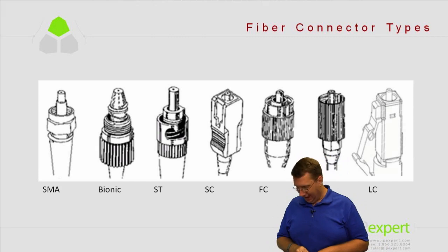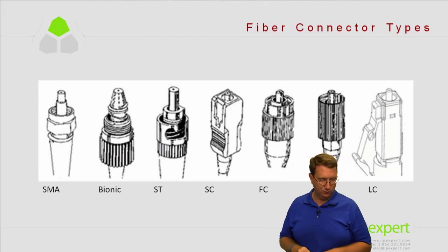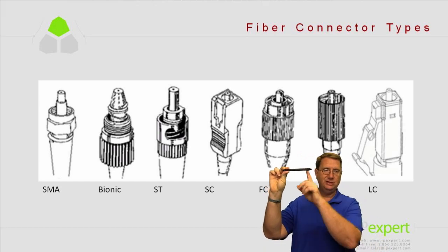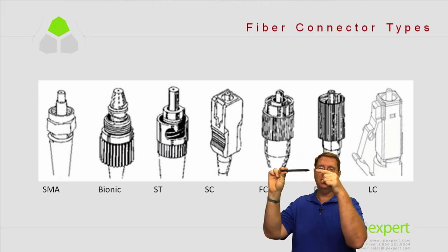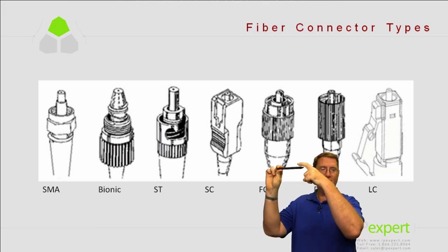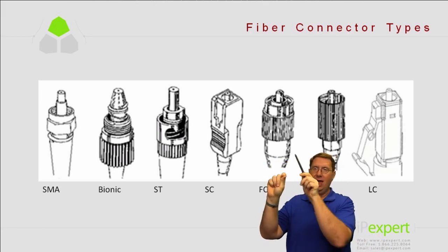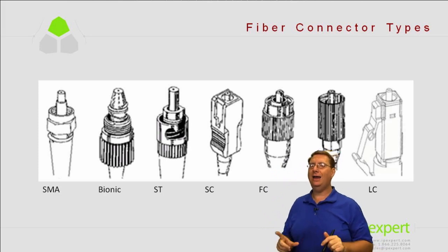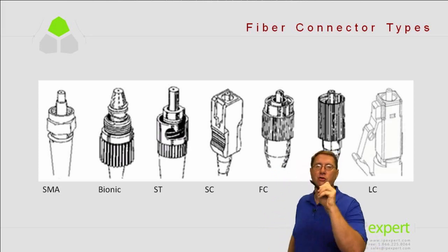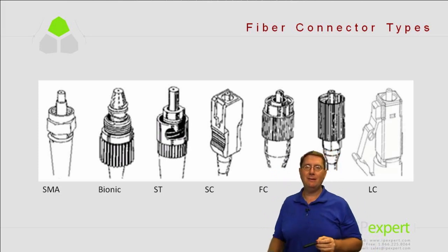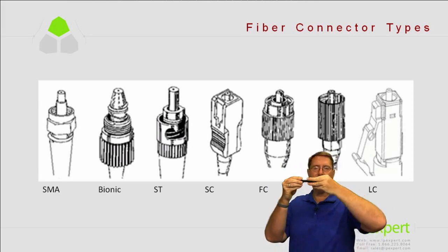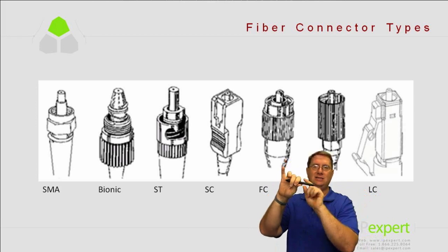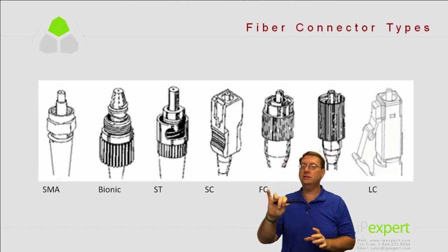Imagine that I'm looking for something that I could physically use. I don't have anything. But imagine that this pen is my fiber optic cable. This is the actual core. So the light is traveling through this pen. Now, if I take this pen and I bend it at greater than a 90-degree angle and at a radius that's less than 30 millimeters, what ends up happening is the cladding, which is that microfiber that's wrapped around the core, gets pushed up against the core itself, if the core doesn't break.